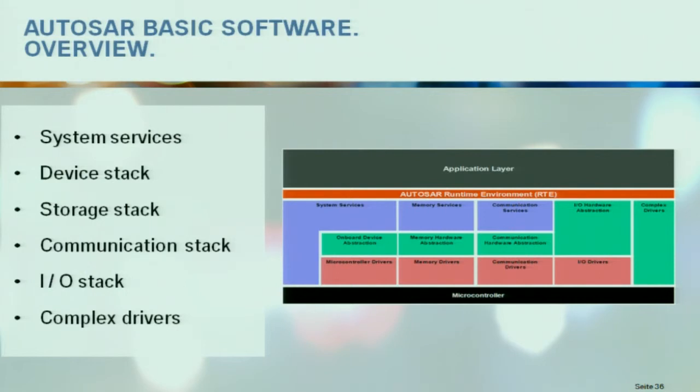The storage stack abstracts between different types of memory. You can have flash memory, you can have EEPROM, and you can even have external flash or internal flash. The memory stack provides a uniform interface to all those stacks so that the application does not have to take care to which storage stack the data go. It has to be configured only in the runtime environment.